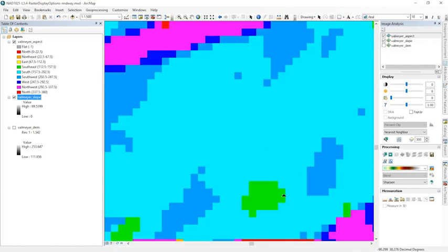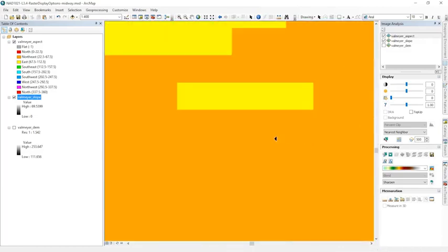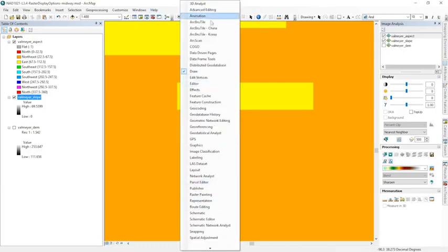And we can kind of see it in here, but if I'm zoomed in really far, or I have giant square areas, it could be hard to tell maybe if this is 2 pixels tall or 1 pixel tall. I could assume it's 1 pixel tall, but maybe this whole area ends up being actually 2 pixels tall, and I just can't tell because it's all aligned and it tends to change by 2s or something like that. So if I want to confirm that, I can use the pixel inspector, which will also show me all the values. And to do that, we need to customize our toolbars and add a new tool.